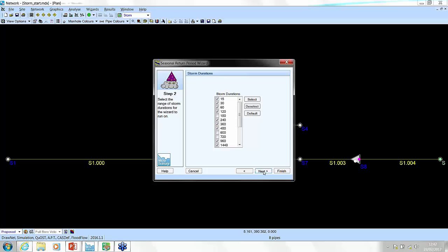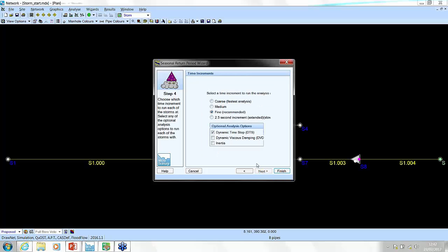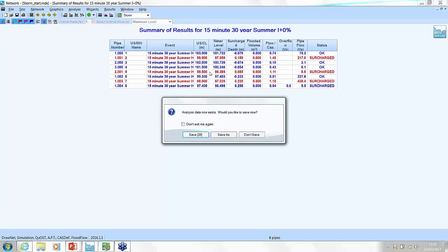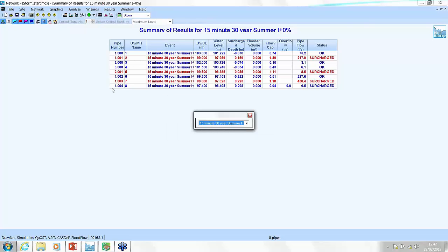Okay, same storms, same 30-year return period. Big issue about stability, always check that. Hot start number 20 is how I do that. And then run that through. Okay, so remember when we get in here, we have to make sure that we've got the worst case storm. This is the magic button to pick that.